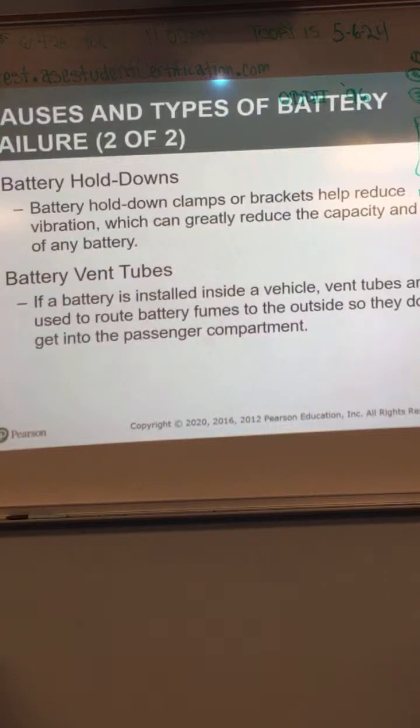I had a friend with a BMW, the battery's in the back. He bought a brand new battery and that thing just died. It's been 4 months. He carries a trickle charger with him everywhere he goes. Yeah, that car's got a parasitic draw on it. It's got something that's not shutting down, it's drawing on the battery all the time.